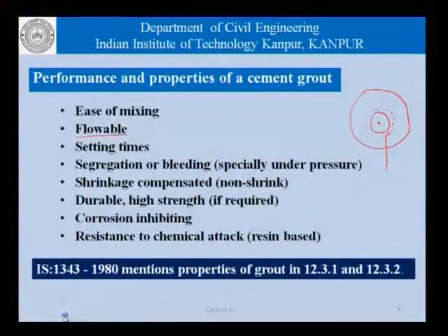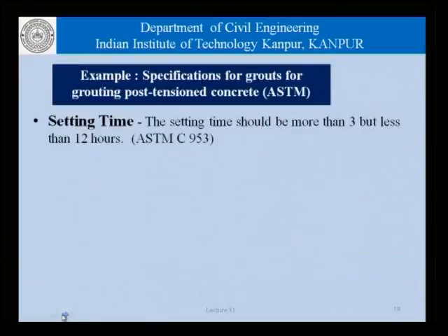As far as specifications are concerned, for example, in India, IS 1343 mentions some of the properties that are required as far as grouting in pre-stressed concrete construction is concerned in sections 12.3.1 and 12.3.2. As far as ASTM standards are concerned, some examples of performance parameters are that the setting time should be more than 3 hours, but less than 12 hours.